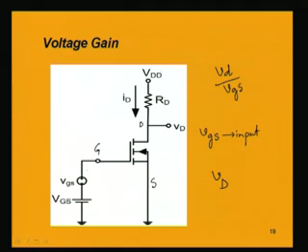These two voltages are there to make the gate to source voltage positive. That means the gate is kept at a voltage positive with respect to the source. Similarly, the drain is kept at a voltage positive with respect to the source. These two conditions must be met in order to make the MOSFET on, or make it conduct.